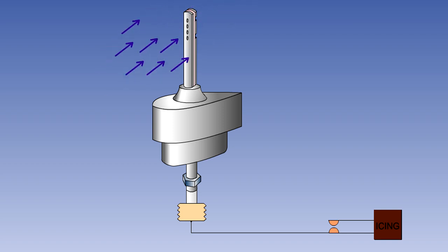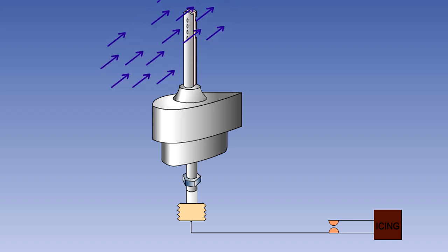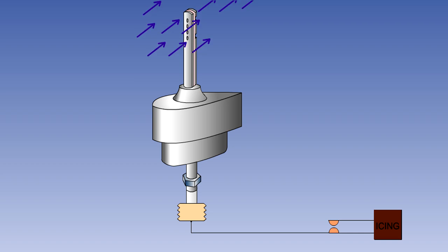In flight, under normal conditions, the air enters the 4 front holes more quickly than it can exit by the rear 2. This causes a pressure build-up in the tube, which is sensed by a capsule connected to its base. The capsule expands, keeping a pair of electrical contacts apart.